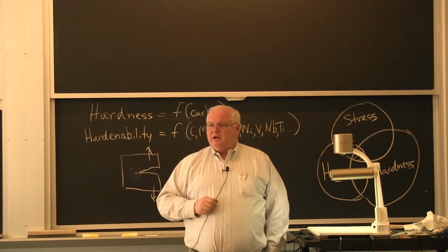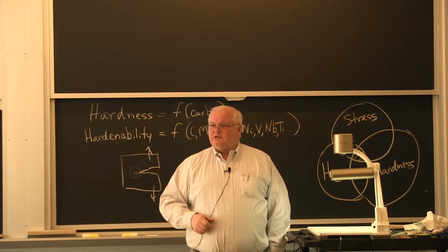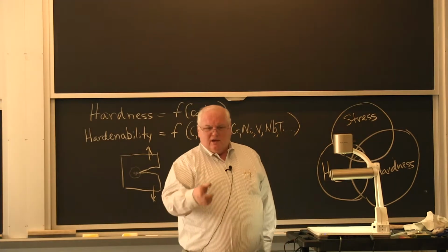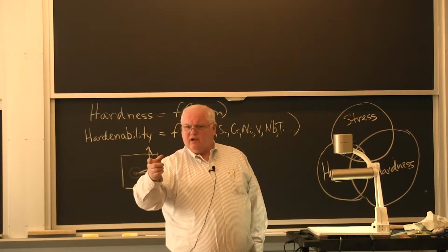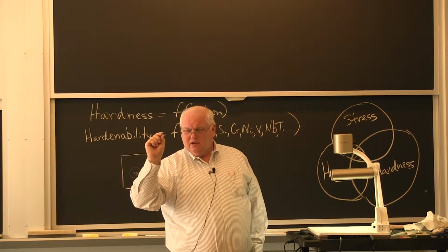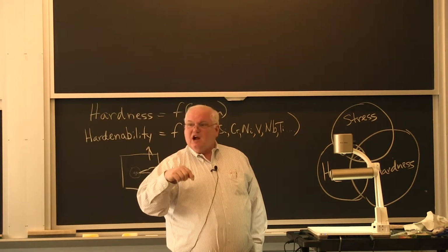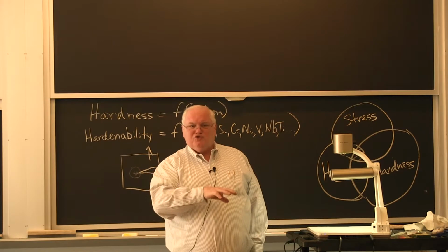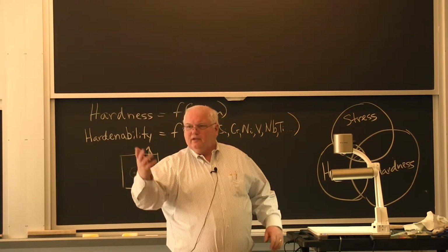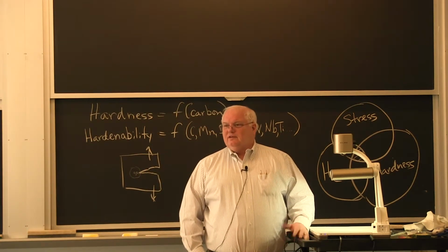You can use cellulosic electrodes. You're welding a regular old pipeline, the root pass goes in as 6011, cap passes go in as 7018. Those were the same diameter of steel rod, but the 7018 was much thicker on the flux. That's because it contains iron powder in the flux, and it gives you a higher deposition rate. You can weld faster with 7018 than 6011.